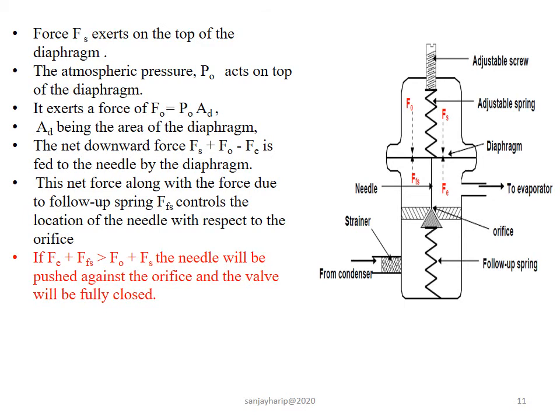If evaporator pressure and spring force is greater than the upward force, that is Fo plus Fs, the needle will be pushed against the orifice and the valve will be fully closed. So there will be no transfer of refrigerant from condenser to evaporator.